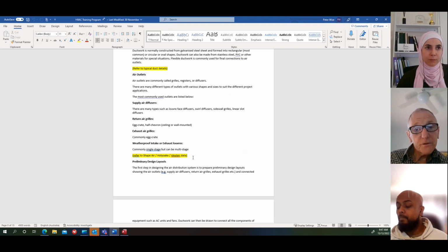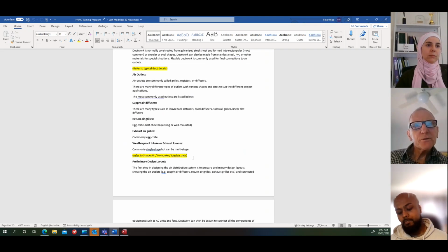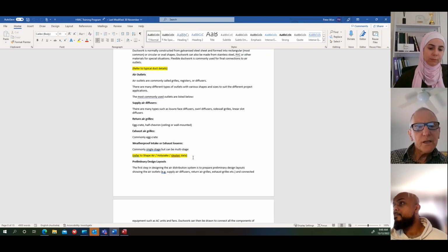This can be quite difficult to find out, actually. And, you know, I've many times had to ask the questions to try and find out what they're using. They keep changing their mind. But the NCC now says that the pressure drop cannot exceed 30 pascals for a single stage louver, etc.